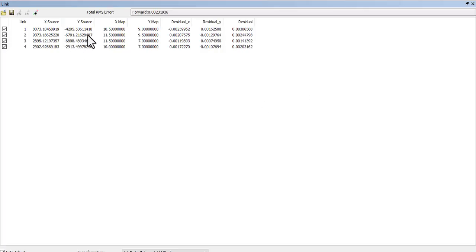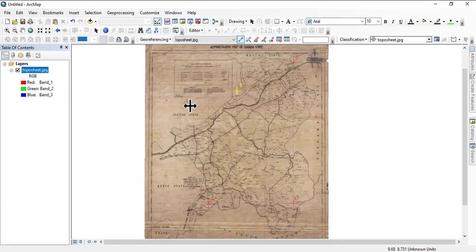Now, if you look at the 4 points we have selected, these are our coordinates of x and y, and then these are our residual for x and our residual for y. Like I said yesterday, it's supposed to have a residual of minus 0.0000. So we have a minus 0.002, a 0.002, and a final residual of 0.0. All of them, you can see that I have at least 0 in 3 places. So this is better than the one we did yesterday.